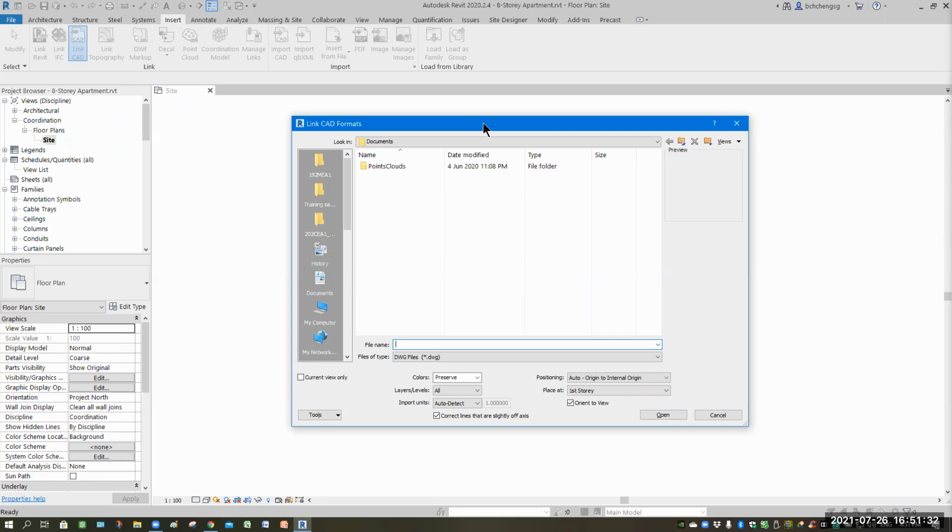In Revit, if the surveyor gives you a text file, then you use the text file to convert. If they give you an AutoCAD file, then you select it as an AutoCAD file. I will show you the CAD file method first, because what I'm giving you is based on the CAD file method. So this one is a must to understand.